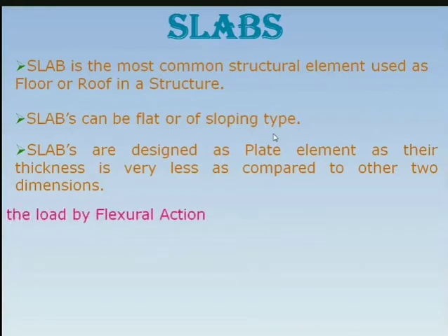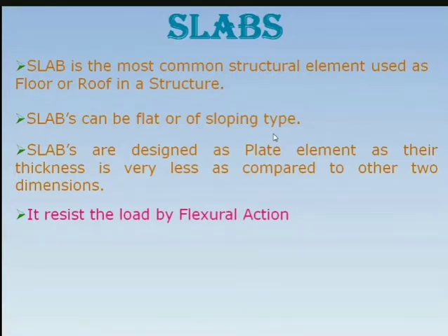Then further, it resists the load by flexure action. Now, what do you mean by flexure action? Flexure is nothing but bending. So it resists the loads by bending action. It undergoes bending and resists the load coming on it. That means once flexure comes, our normal formulas come into the picture, that is WL squared by 8 and all those formulas which you have used, once we say the load resistance is by flexural action. Flexure action means simple bending action.